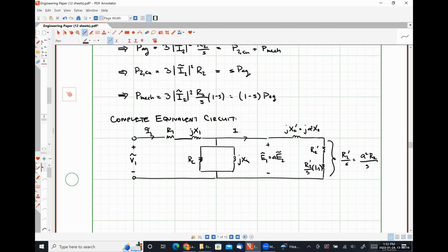Here is our secondary or rotor current referred to the stator, I2 prime, which is just our rotor current at the rotor divided by A. And I'm going to throw a dashed line right here to let you know that everything to the right of this line is the power transferred across our air gap.